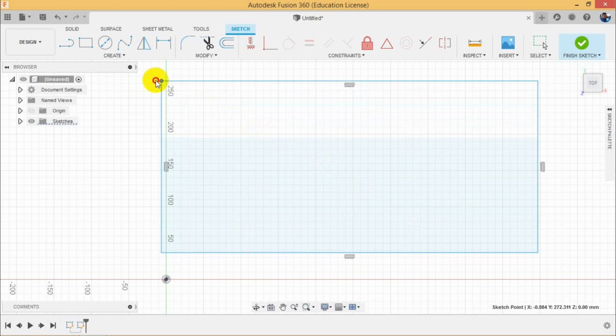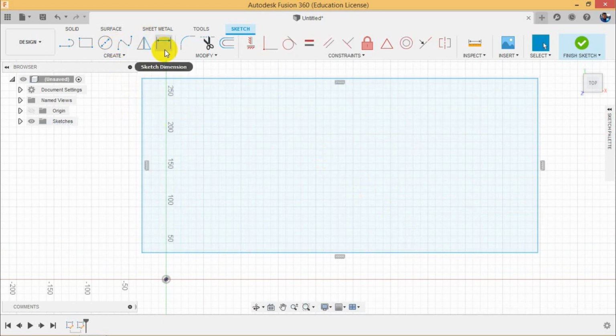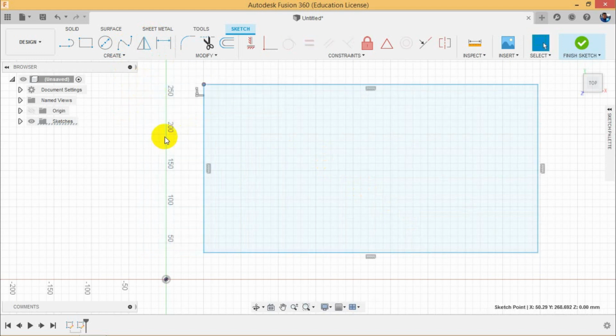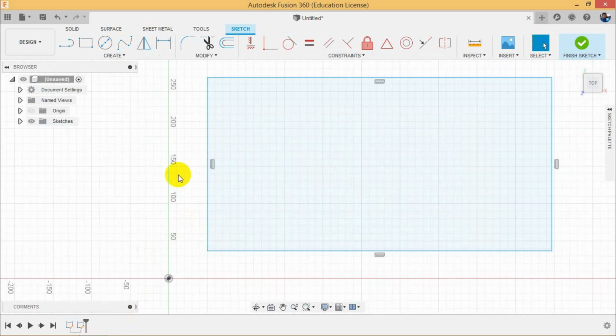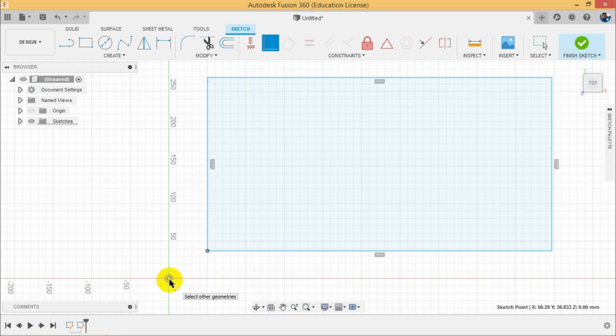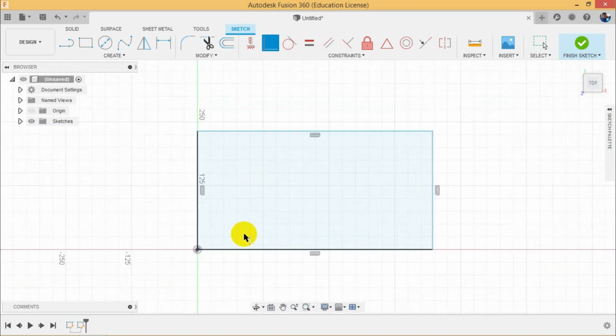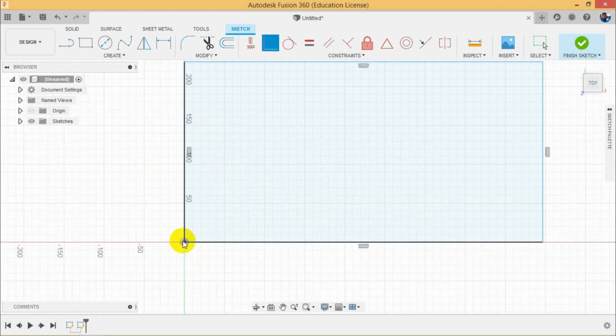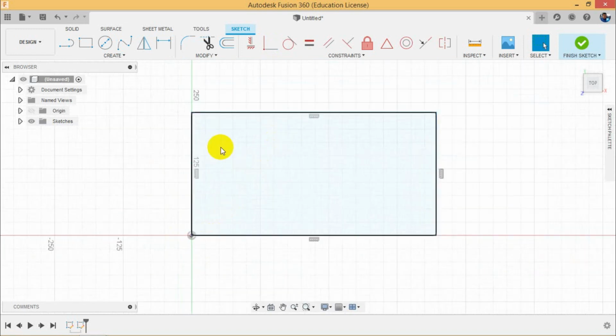They can be small in size or large in size. As I didn't put the dimension yet, that can be changed, but the horizontal can't be vertical, or the vertical cannot be horizontal if I apply sketch relations in here. Now I want to make a coincident relation with this point to the center of the origin of the sketch. So you can see I made it fixed in here, as the origin is fixed. So that's a good thing to put position of the rectangle.